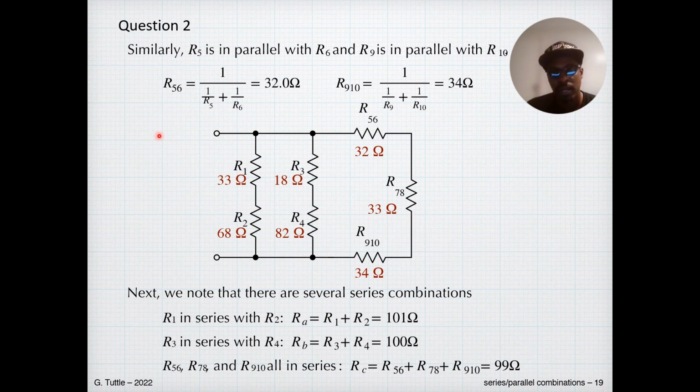And remember, apply the formula, 1 over the reciprocal, 1 over single resistors, all right, plus all of them, all combined. So always it's the reciprocal of the resistors, or 1 over the resistors, all right? That is in parallel. Then you do the same for all of them.